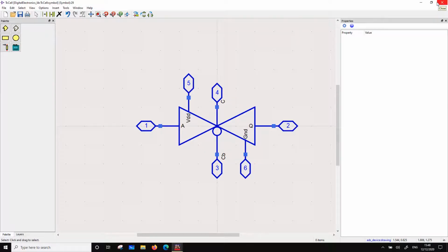So now this means that I can create a high impedance state between A and Q. If I have two paths to the output, for example, which I'll see in the next circuit, which is a multiplexer, and I ensure that one path is off, then the outputs can be directly combined. In gates, you cannot combine the outputs directly, because you will be shorting the supply to ground under certain logic input situations. In the case of transmission gates, you will not have a problem, because one of the branches can be high impedance. So that's why you can connect the outputs of two branches together.